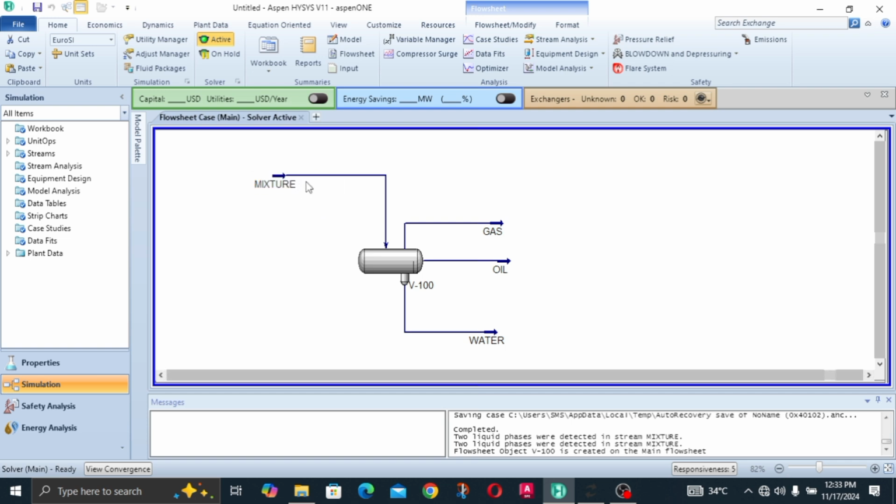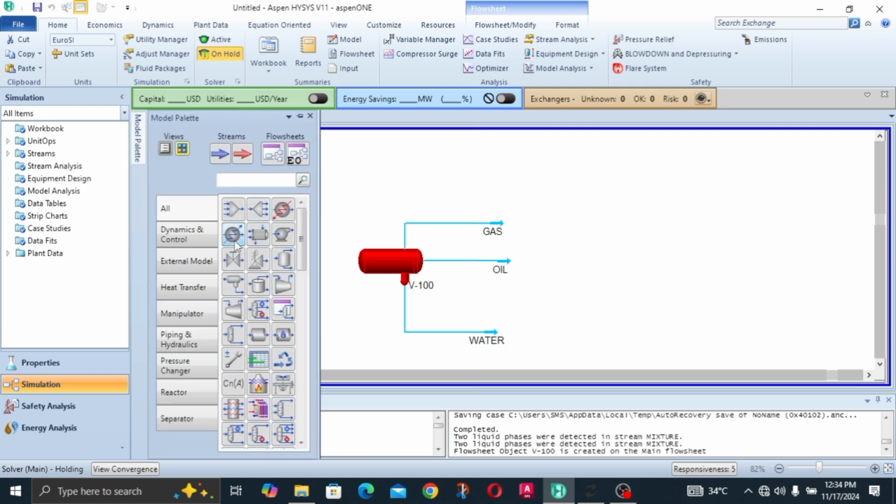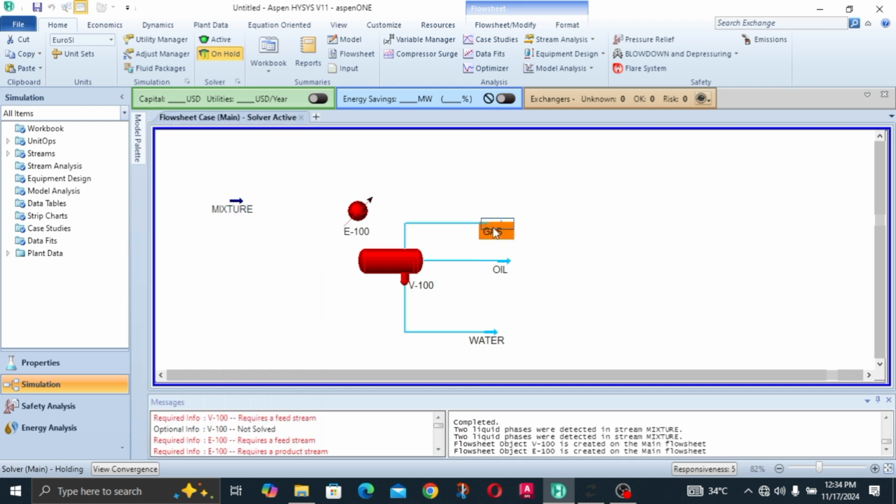What it's basically telling us is that the mixture is actually more of a vapor. It's too hot, so as a result, the vapor fraction is very high, which results in the water evaporating together with the methane and going out in the gas outlet. I'm sorry if I sound a little bit off track, but it's going to make sense in a jiffy. So we're going to disconnect this and do a little bit of condensation so that the water present inside the gas outlet would be where it's supposed to be, in the water.